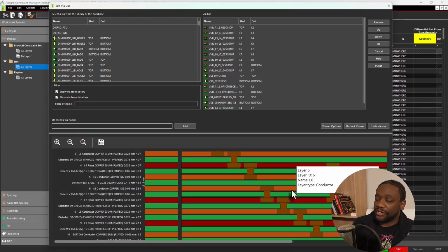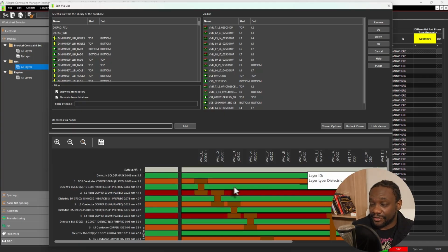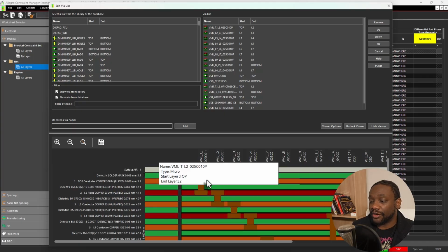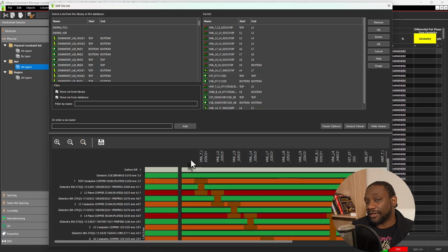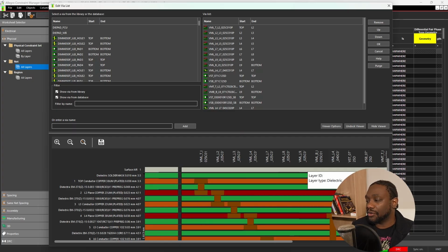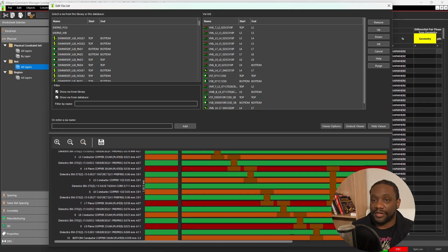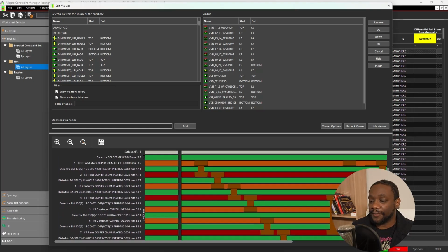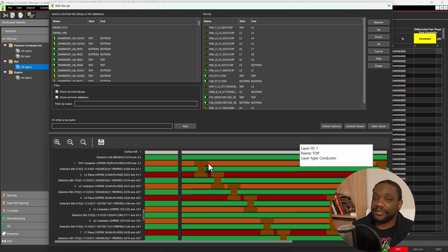So engineers came up with a method to limit where the signals can travel, and that is the blind via. The blind via is one where you start at the top layer for your via, but you stop at just the layer you need the signal to be connected at. So say layer 1 to layer 2, or layer 1 to layer 4, and so on. That's a blind via. What's the blind part? The bottom hole of the via, we can't see. We're blind to it. But the top side, we can see.